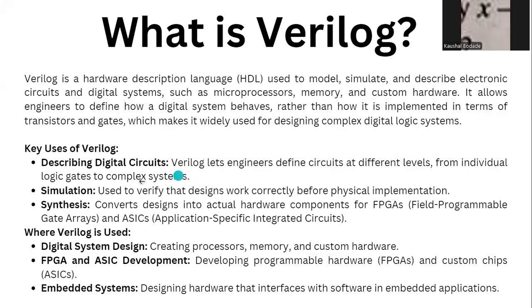Simulation is used to verify that a design works correctly before physical implementation, which means it helps us simulate everything before implementing it at a physical level. In synthesis, it converts the design into actual hardware components for FPGAs, meaning field programmable gate arrays, and ASICs, meaning application specific integrated circuits.